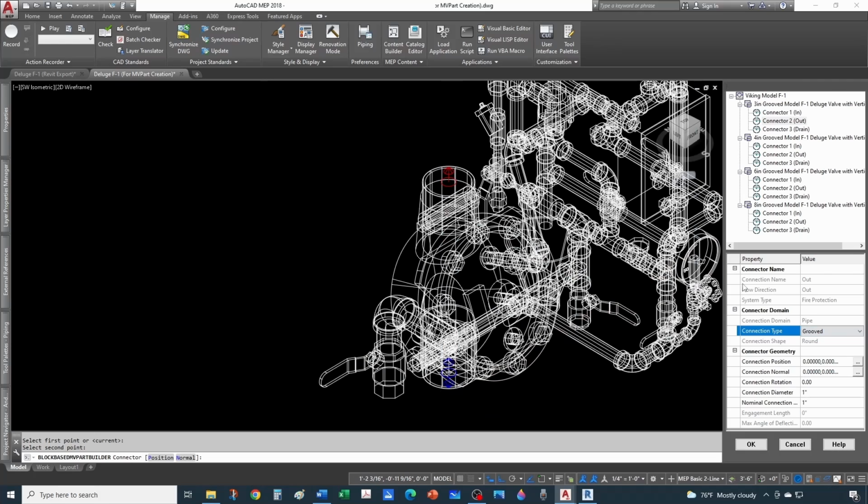And oh, we forgot to change the pipe diameter in the other one. So let's go to our end connector, and then we know this is a 3-inch. So here just select 3 inches and then 3 inches as well. I don't think you have to use the symbol of inch. See, it doesn't really matter. Now let's go to connector 2, and that was also 3 inches, right?